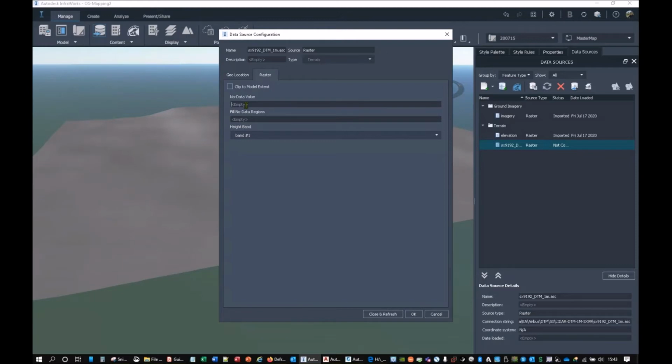I won't go into too much detail, but basically an ASCII grid, a GeoTIFF file, all of these are raster files, like an image file. And they're exactly the same as an image file. If you imagine an image as a rectangle, and on that image, it's got lots of pixels, and each pixel has 3 numbers on it, RGB, red, green, blue colour. This is exactly the same as that, except that pixel has X, Y, Z on it.